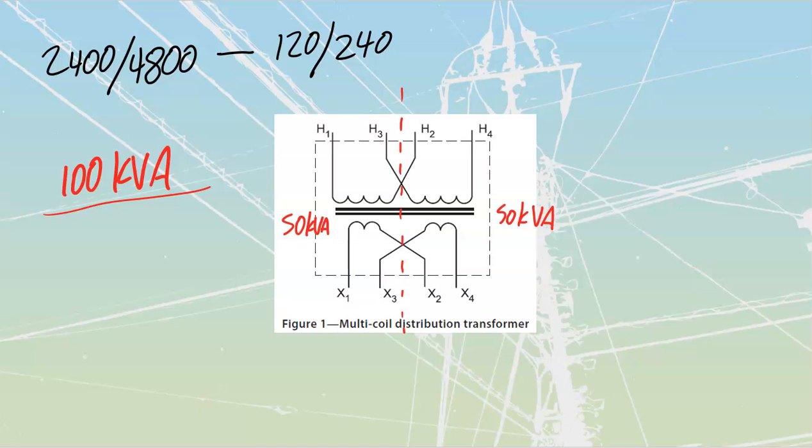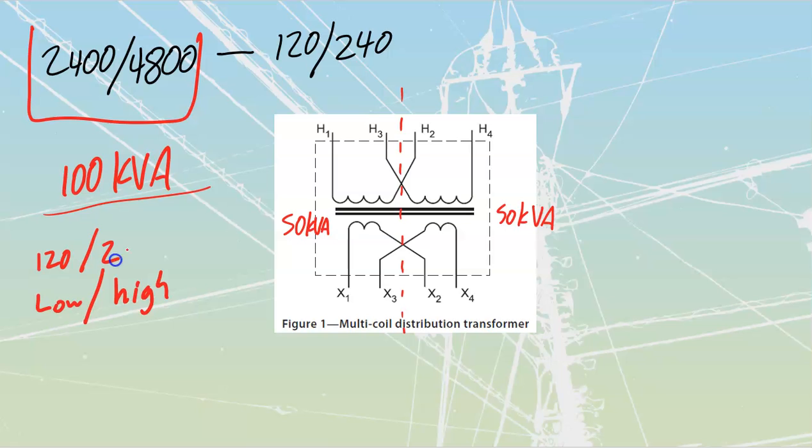And the standard notation identifies a couple of things for me. This over here is done properly in standard notation. Standard notation tells me that this is a single phase transformer, and I know that because it goes with the low, then the high in the slash rating. If I have a 120/240, I know that whatever that piece of equipment is, it's designed for single phase.